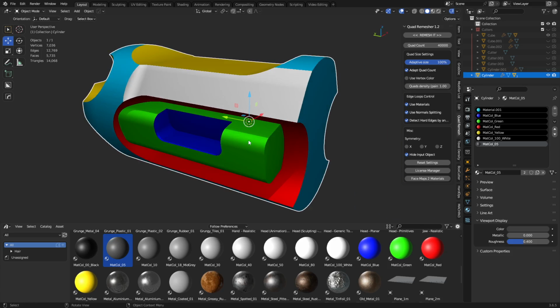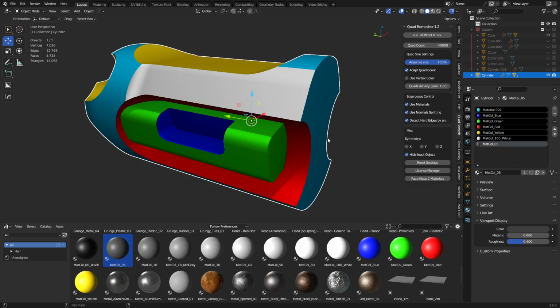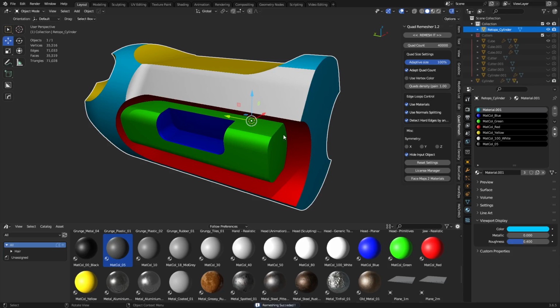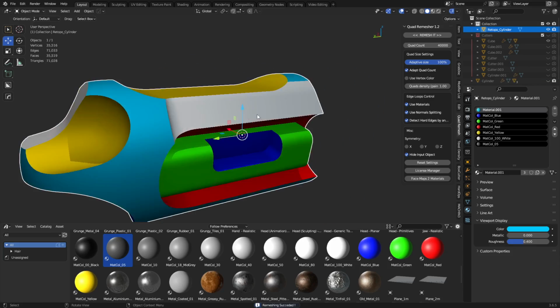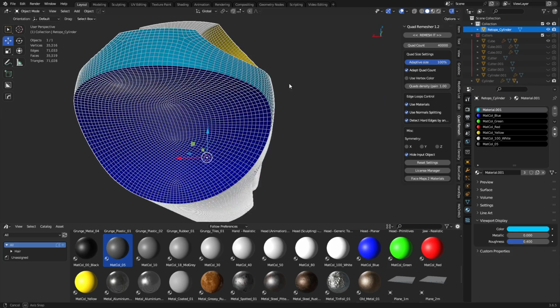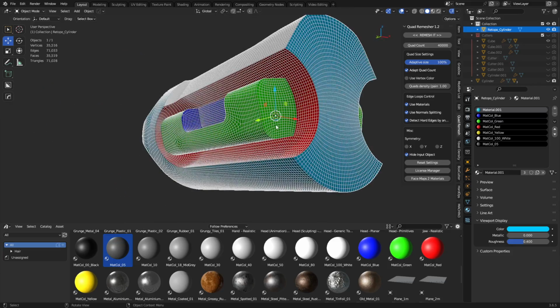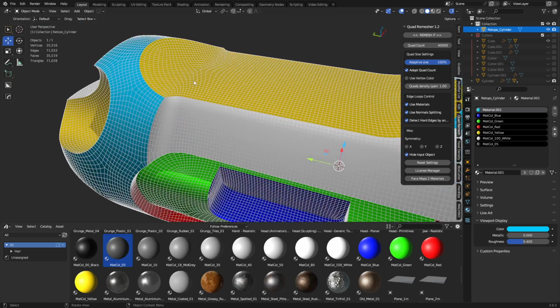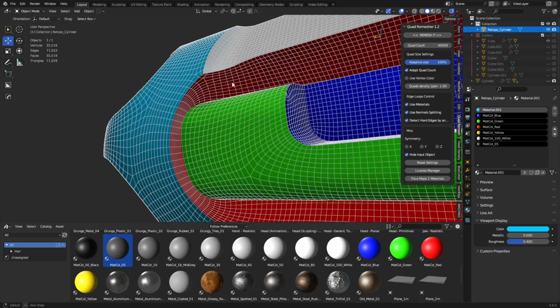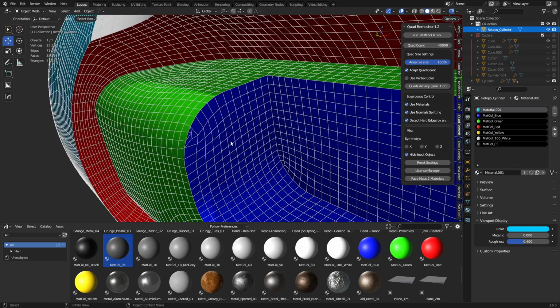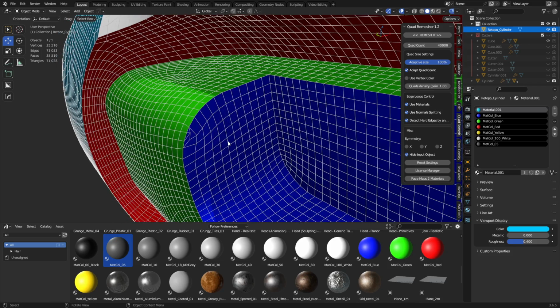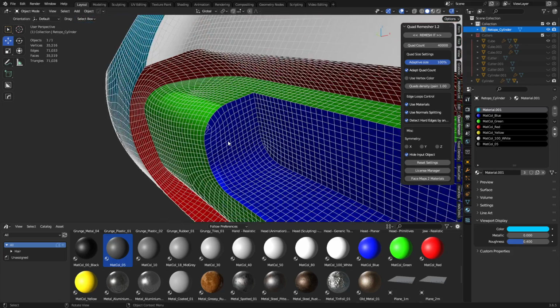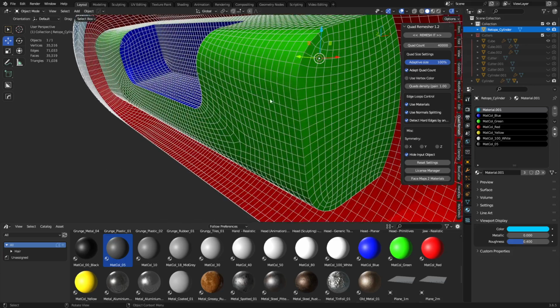As we go through this process now, we're just going to hit remesh. We will still more than likely get errors. We sometimes still have to fix things manually, but for the most part, it does pretty well. It's just remeshed just that fast. Not a big deal. Okay. And we could probably find some errors in here if we look really closely. Sometimes you have some weird poles in areas. Sometimes just things go wrong. In this case, this was kind of an ideal situation. Usually, if you focus on bigger shapes, primary and secondary shapes, it works out quite well. When you start getting into tertiary stuff, that's when you're going to have a lot of issues.